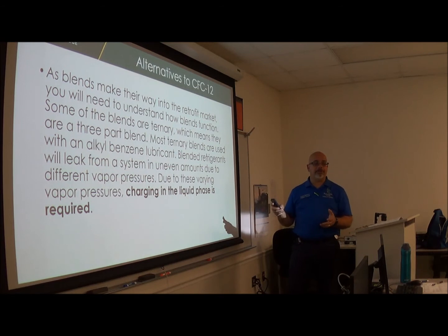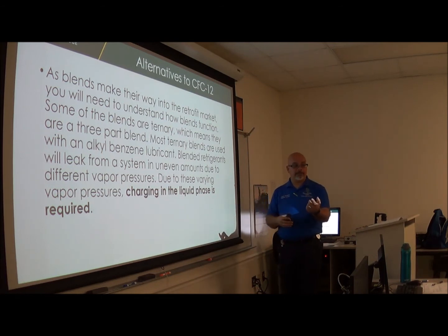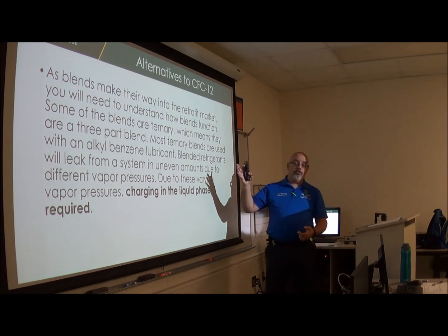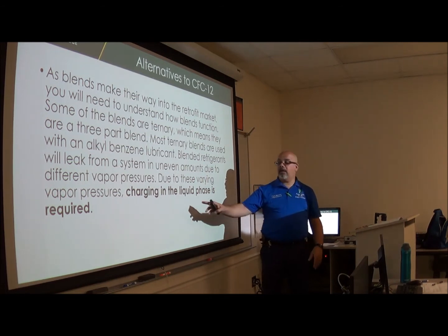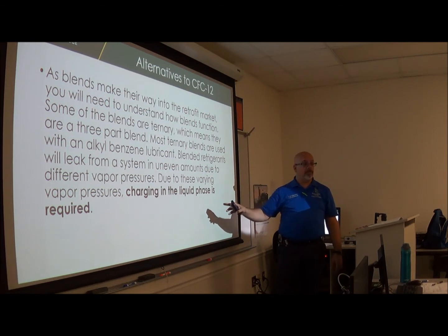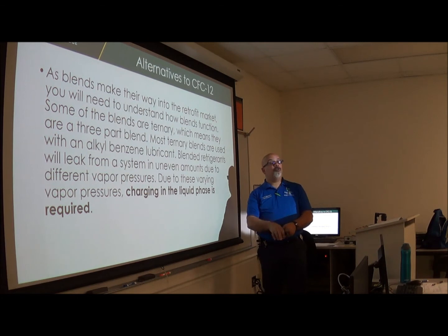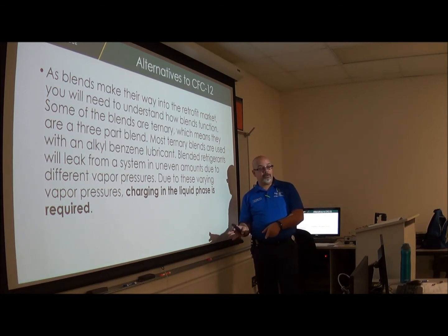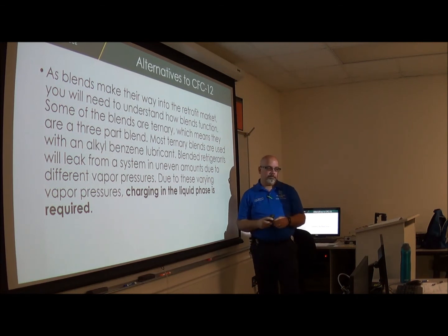So we normally charge a vehicle with the cylinder up straight like we're supposed to, through the low side. If we're going to be using a blend, which we should not be using, but if we're going to use it, we have to charge in a liquid phase, which means we're going to charge through the high side of the vehicle, and we have to turn the cylinder upside down.